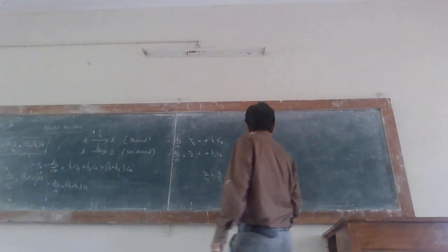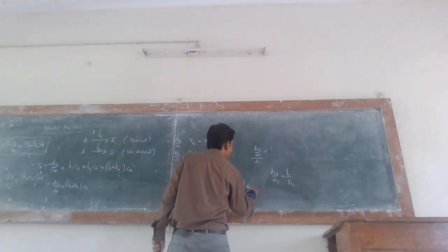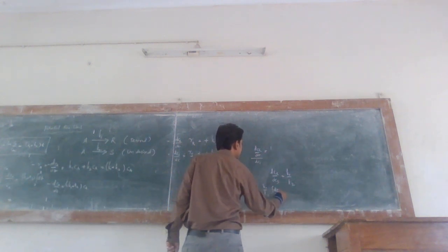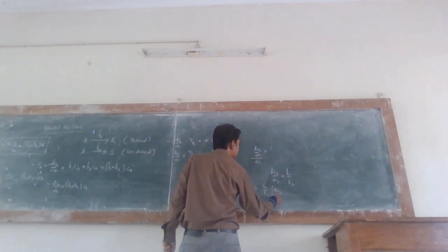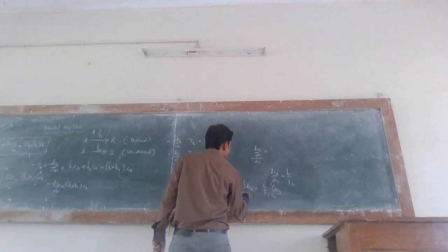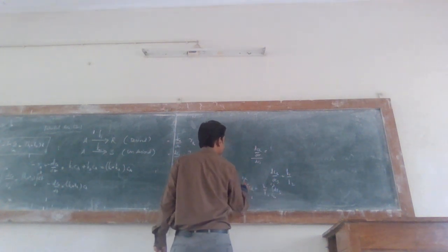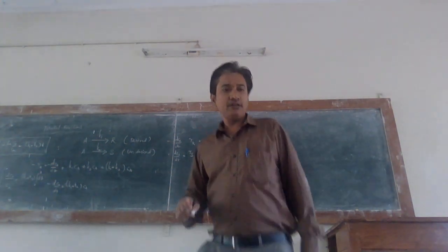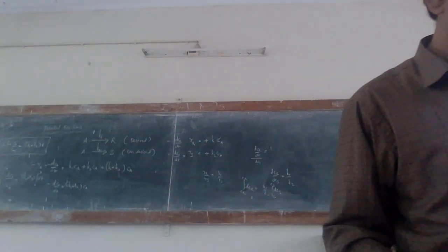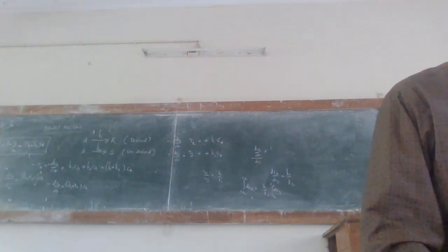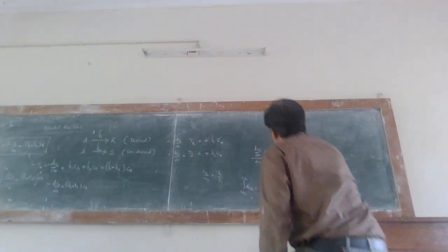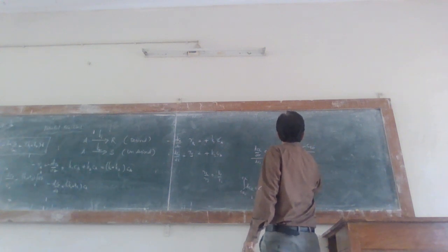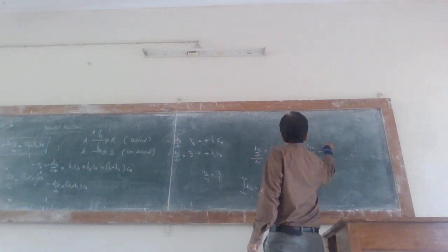Now you apply the limits here. Maybe I can say the integration of dCR is equal to K1 by K2 into the integral of dCS. Let us apply the limits CS0 to CS, CR0 to CR, that is initial concentration to final concentration of product. So I will end up with the expression CR minus CR naught by CS minus CS naught is equal to K1 by K2.